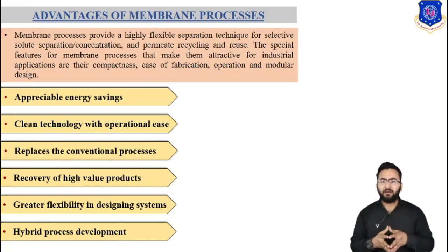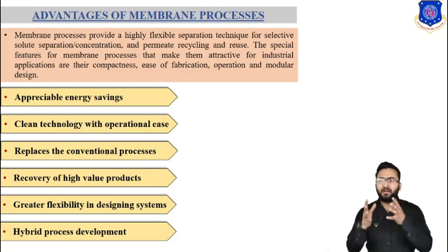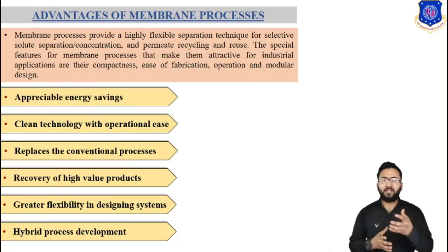Since membrane separation does not require a change in state of the solvent to effect the dewatering, this should result in considerable savings in energy. The second advantage of the membrane separation process is that it is a clean technology with easy operation. No complicated heat transfer or heat generation equipment is needed in membrane operation. This process can be operated at ambient temperature.